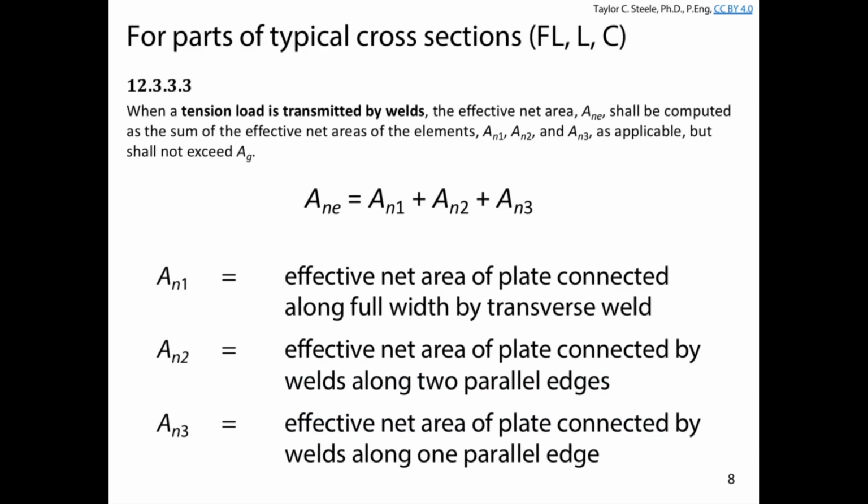But we're also going to have situations where some of the components or some of the plates of the cross-section are connected along just two parallel edges, and some where the net effective area is connected just along one parallel edge.